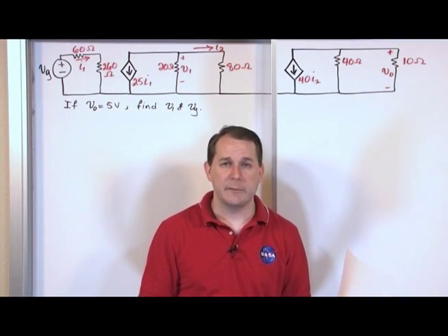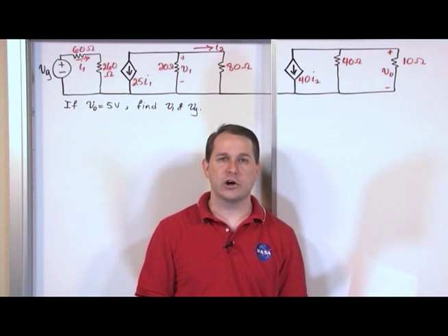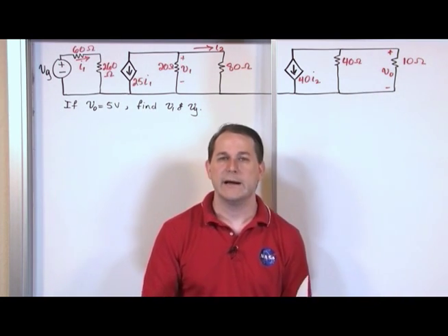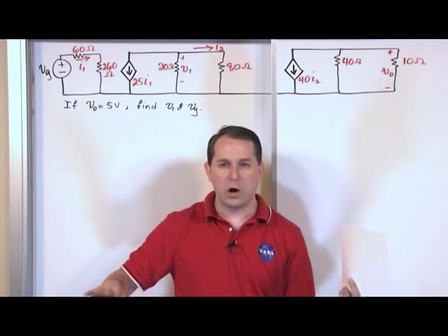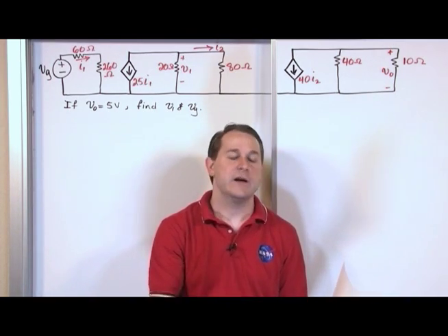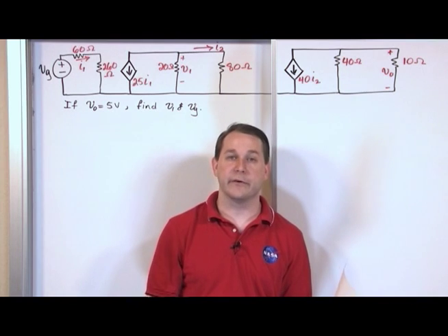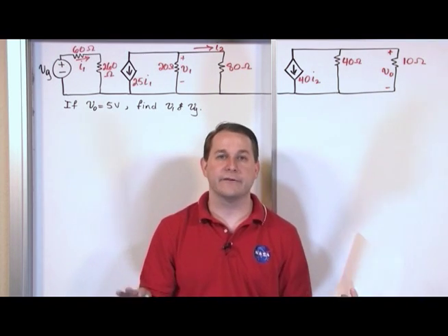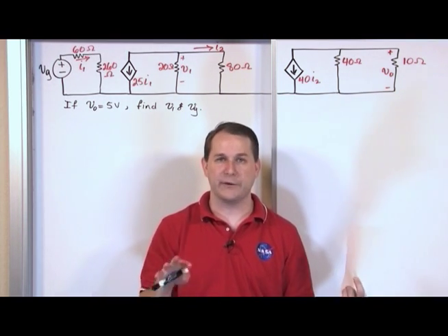So this is very common in a car, for instance. The electronics in a car, they're all grounded to a common point. In your home, all the wall outlets are grounded to a common point, which is usually outside your house. It's literally nailed into the ground. So the voltage reference of your entire house, 0 volts, is a known quantity for everything.